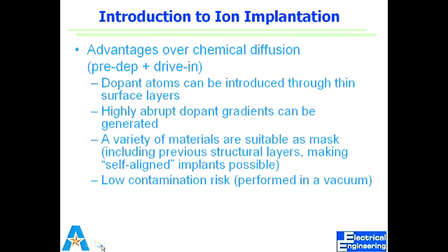Okay, I'm not being very clear about this. You have the tapering edges at the oxide, right? If we use something similar to ion implantation, would you be able to eliminate that, if you use this method? Okay, so those bird's beaks in silicon dioxide are not a function of dopants, right? But you want to eliminate those bird's beaks by implantation. Implantation works by incorporating ions into silicon.